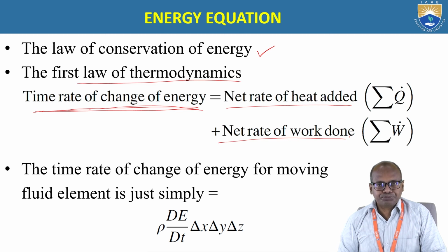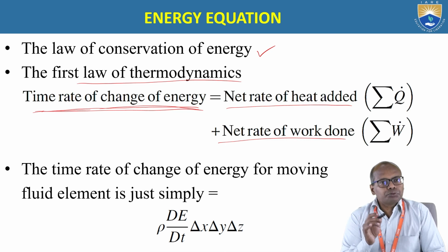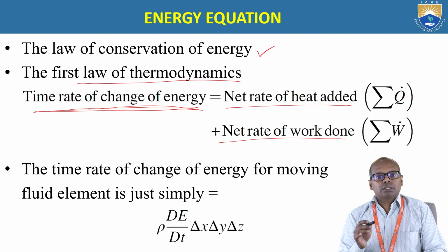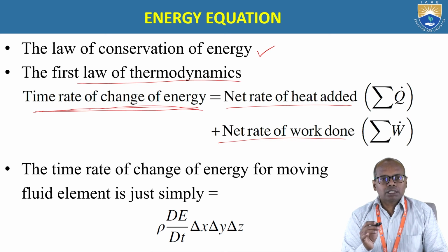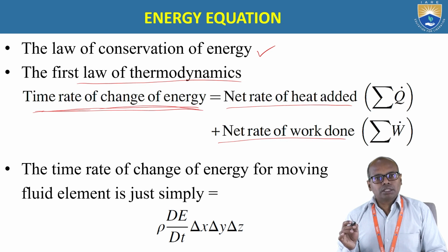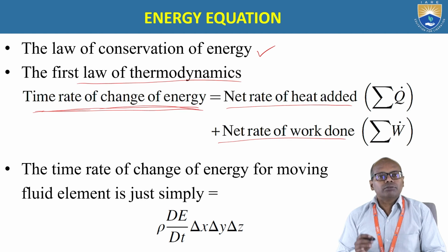The other part is the net rate of work done. There are a number of forces acting on the fluid element, as we have discussed in the last discussion on the momentum equation. These forces will do some work on this fluid element. The surface forces or the normal forces will do some work on the element, because of which the energy inside the element will also change. That we'll see again at the end of this slide.